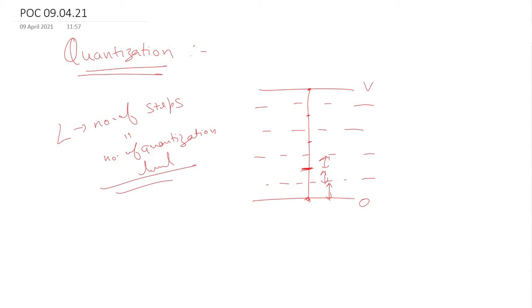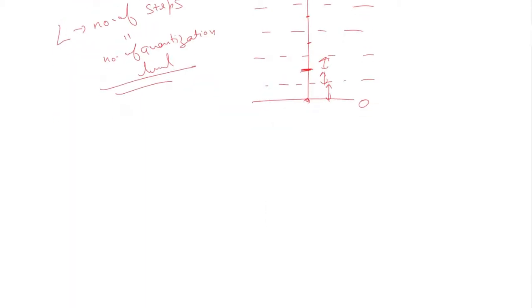The reason why we go for quantization after sampling is so that we can perform the encoding process thereafter easily, because we are limiting the number of samples here. Since the samples will be limited, the number of bits required to encode them will also be less. Clearly, we can see that the maximum value of quantization error can be delta by 2.